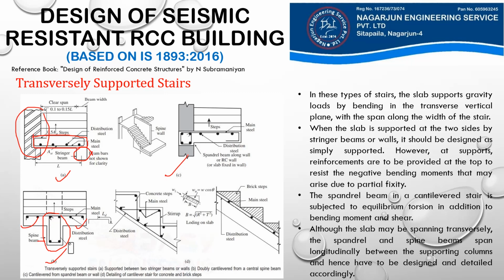And in number C, you see that we have cantilever steps here, and these cantilever steps originate from this spandrel beam, which runs in the direction perpendicular to the paper. This is known as a spandrel beam, and our steps originate from these spandrel beams and are cantilevered in nature.